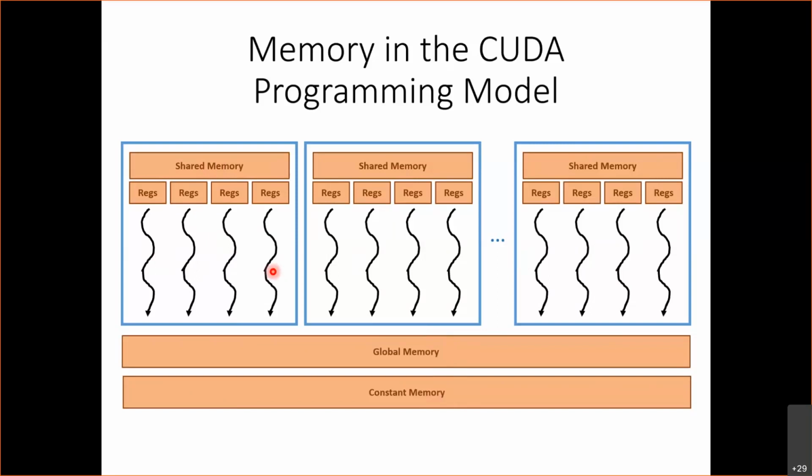Okay. So someone's asking, shared memory, constant cache, and L1 cache are physically unified, right? So that's a microarchitecture detail. For example, in some architectures, they let you configure how much L1 cache versus how much shared memory you want. So you can have a kind of trade-off between shared memory and L1 cache. So you can say, I want more L1 cache, less shared memory, or less L1 cache and more shared memory. So in that sense, they're somehow unified. Constant memory is a little different.